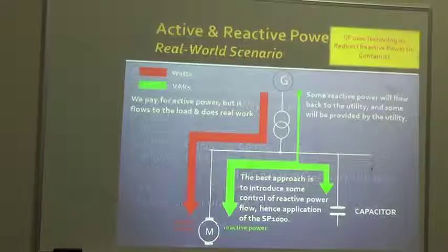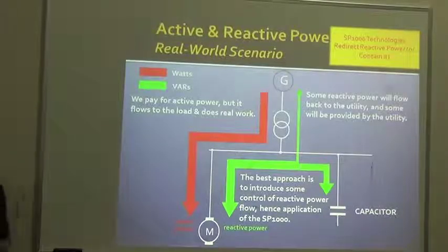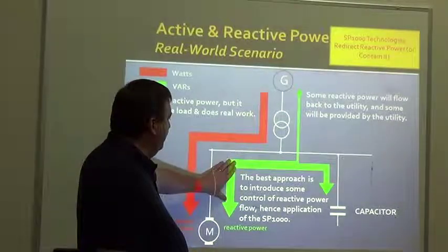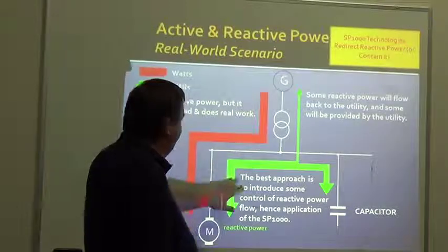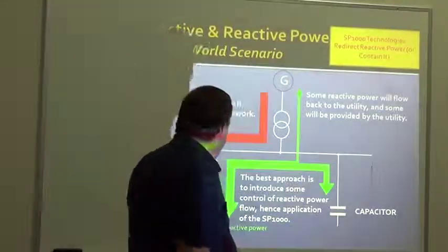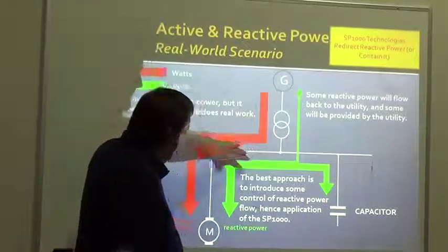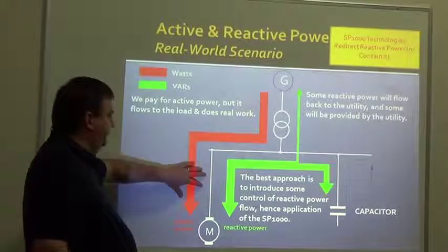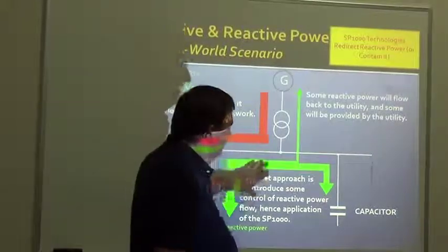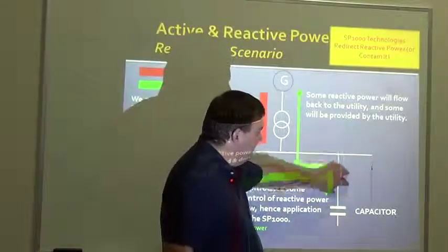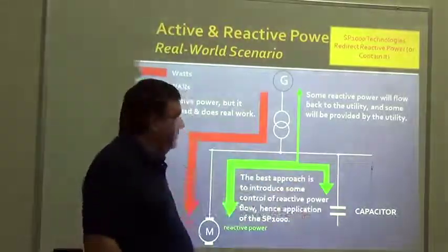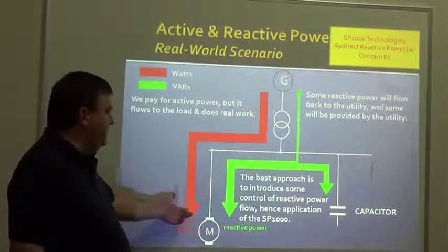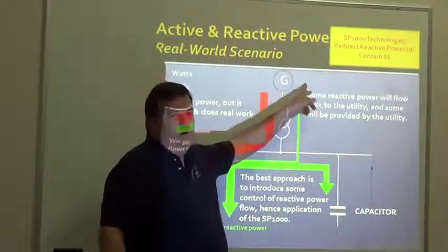You saw this one already, the one on reactive power. Real power, reactive power. If we don't have some kind of correction over here, then we have to supply a lot of reactive power to the loads based on what the real power is, based on the nonlinearities here. But as soon as we go in and start managing this capacitance at certain points in the system, we're able to re-steer the reactive power, or provide the load with the reactive power from this instead of from up here.